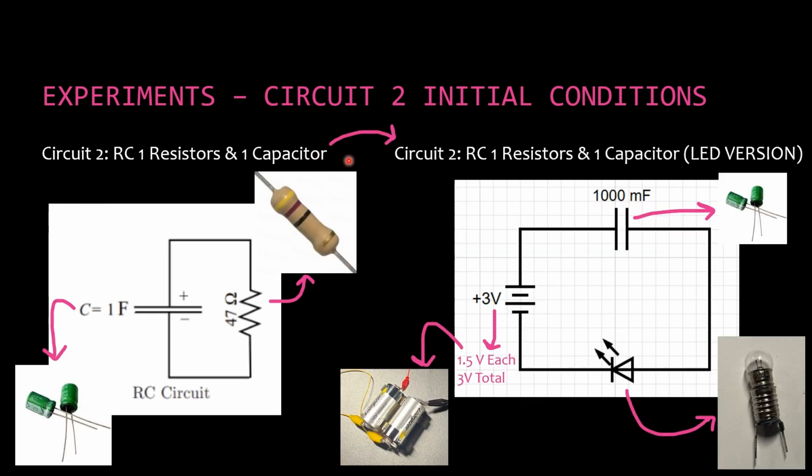Next, we did have to transform this circuit, so we did have to design our own a little bit. Here is the entrance of where we would have our batteries right there. This was removed from the circuit when we wanted to measure the charge and discharge rates of the capacitor accordingly, and we still had our 1 farad capacitor right here, and the only real addition was we put a 3 ohm or 15 ohm incandescent bulb on it to visually see these discharge and charge rates.